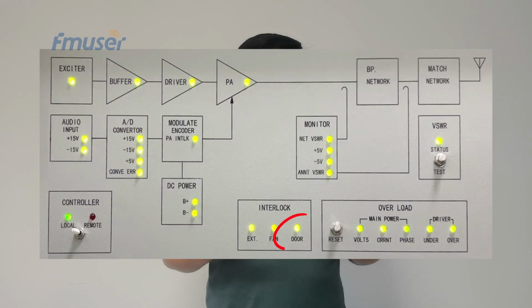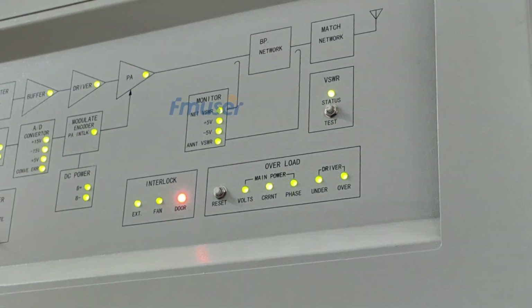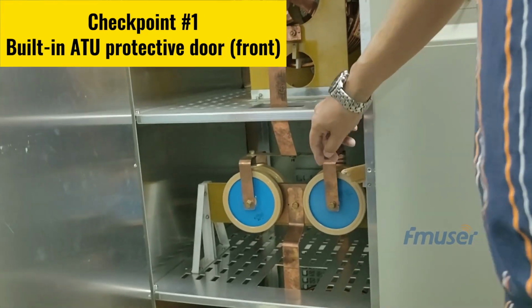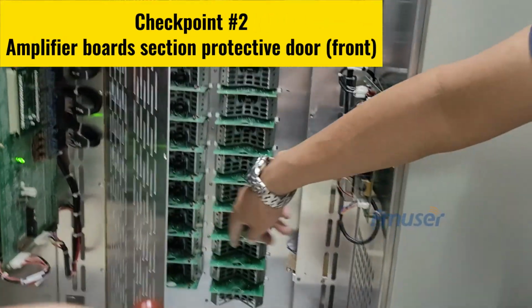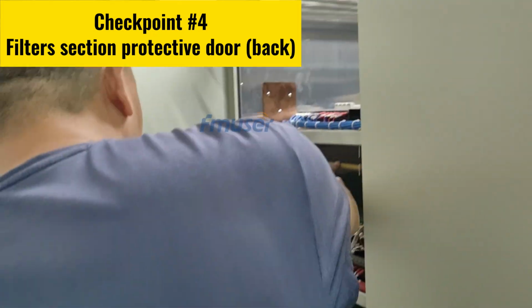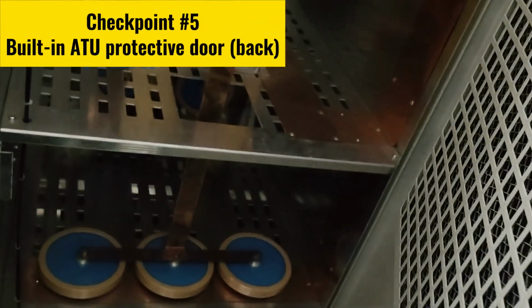This light fault detection is responsible for prompting the operator to ensure that all cabinet doors of the transmitter are properly closed. There are 5 checkpoints to consider. The cabinet door of the built-in ATU space on the front panel. The second layer cabinet door that protects the power amplifier module on the front panel. The cabinet door of the front panel protection transformer module. The cabinet door of the back panel protection filter module. And the cabinet door of the back panel protection built-in ATU module.